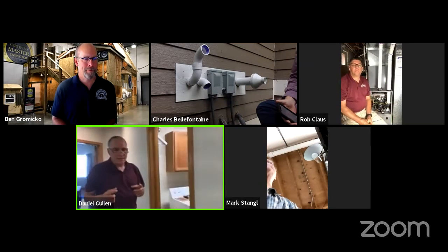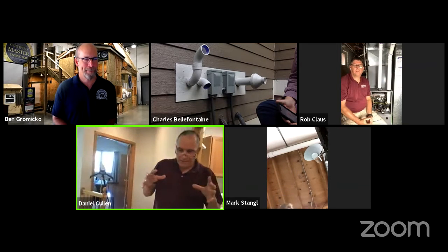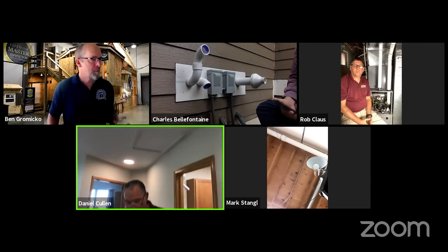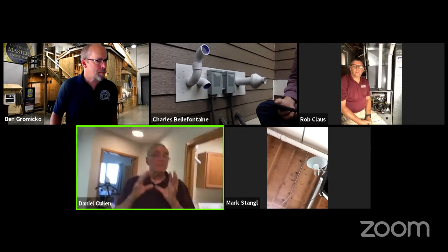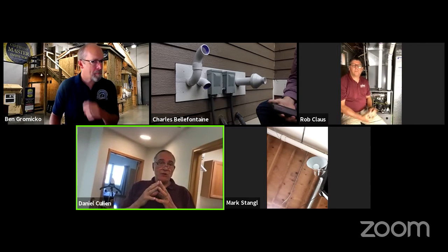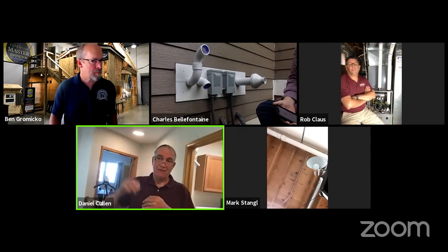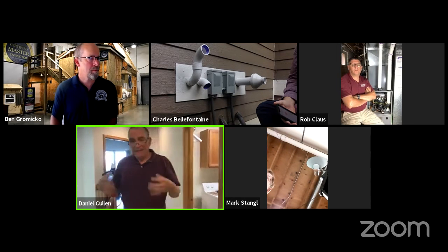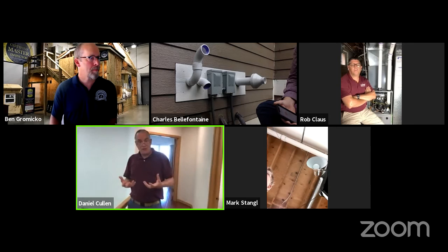And again, getting back to the concept of the HVAC as part of a system. We talked a little bit about solar orientation here and the benefits it brings us in the wintertime. A big part of any house is the attic. If you talk to any weatherization contractors, they'll tell you that when you're trying to save energy in a home, you do A, B, C, right? So attic is number one, because a home has what we all know as the stack effect. Air wants to travel vertically up and out. And that's the air that we're paying to heat and cool. It's also air that's laden with moisture.